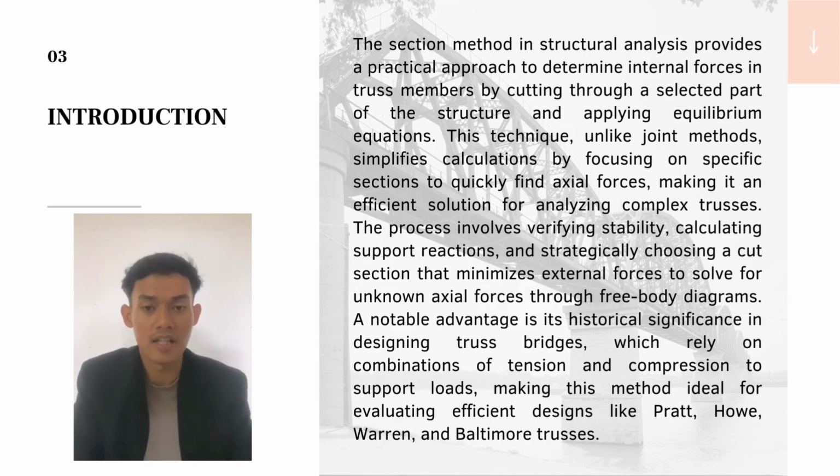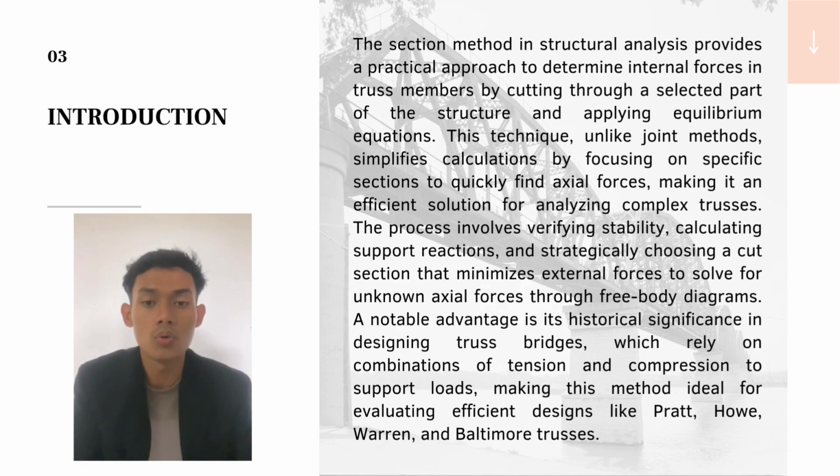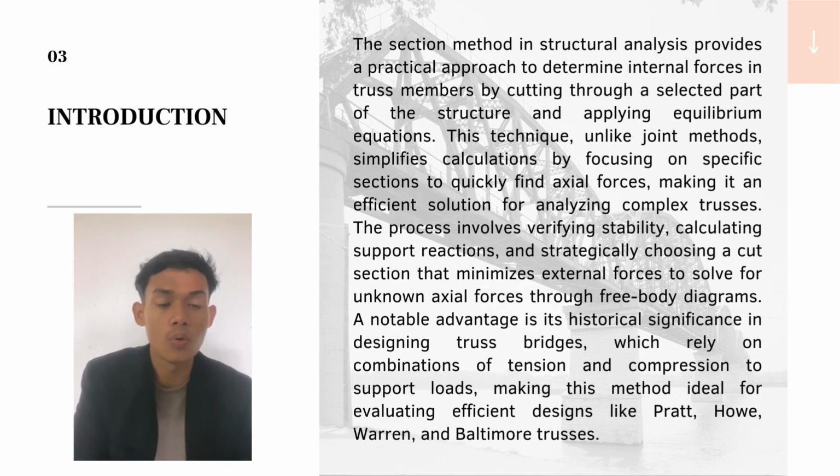Next, for more explaining, the process involves verifying stability, calculating support reactions, and strategically choosing a cut section that minimizes external forces to solve for unknown axial forces through free body diagrams.